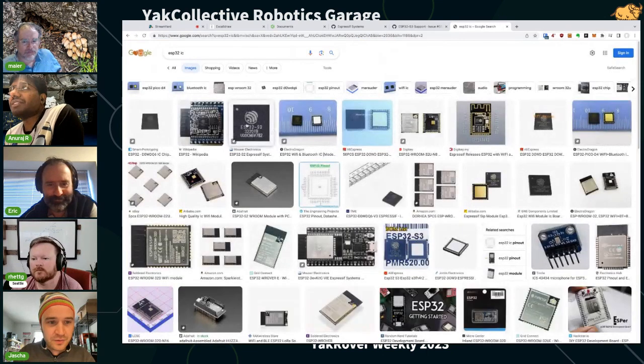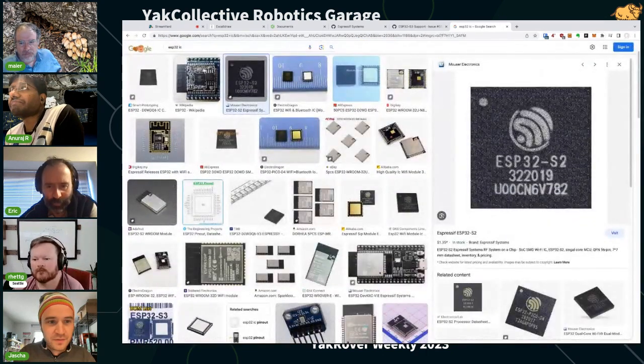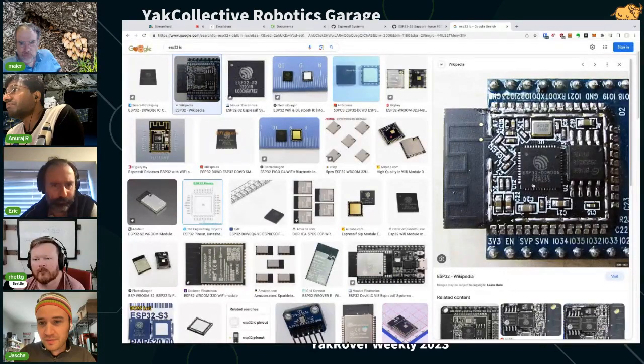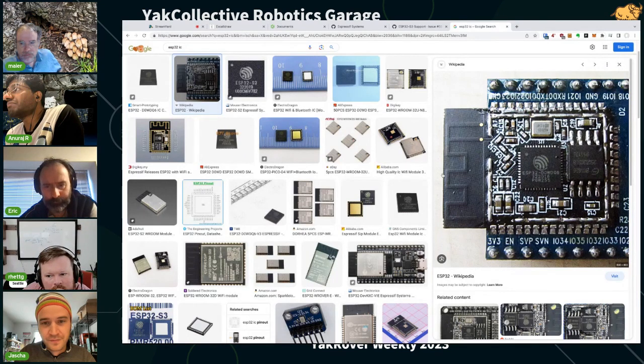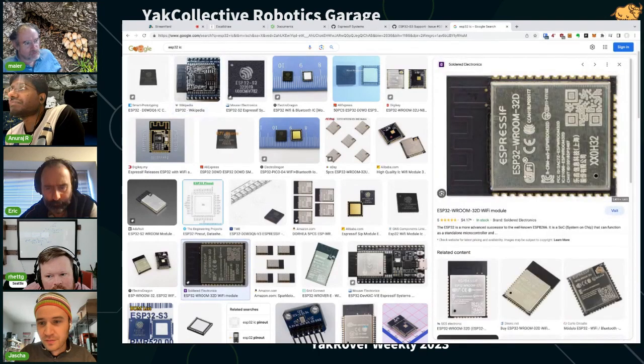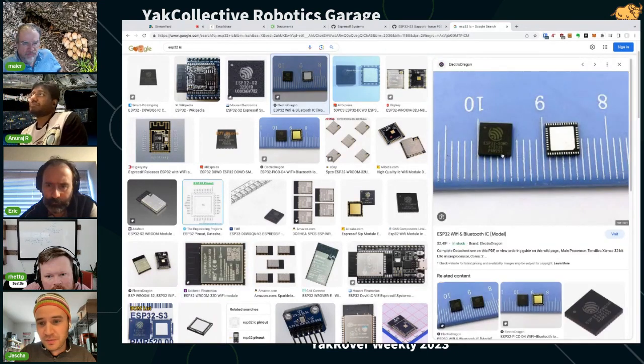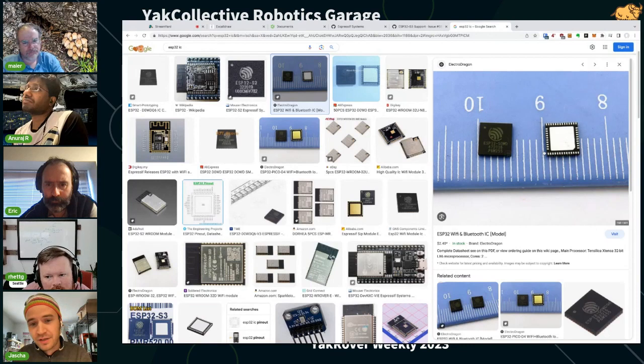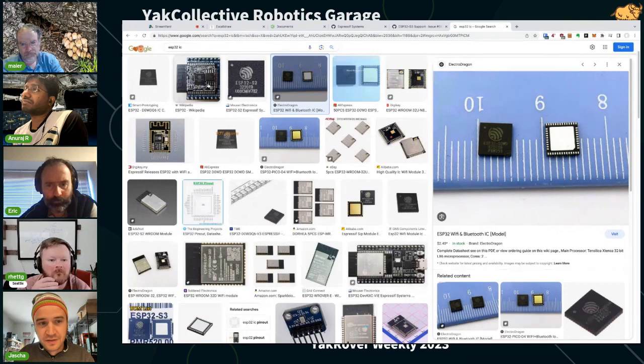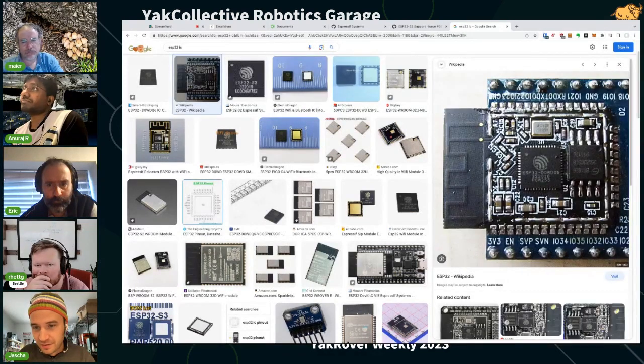Yeah, it's the actual chip packaged. You can see this is without the can on top. So in the little module we're looking at, there's the actual chip inside of it, and then a couple of little support components. And the whole reason for this is that this one has an FCC ID, so it's already pre-certified, ready to go. This is the actual chip, and we can also use just the raw chip, especially if we're not going to use the radio. But buying the module is nice because it's easy to solder, as we discussed.